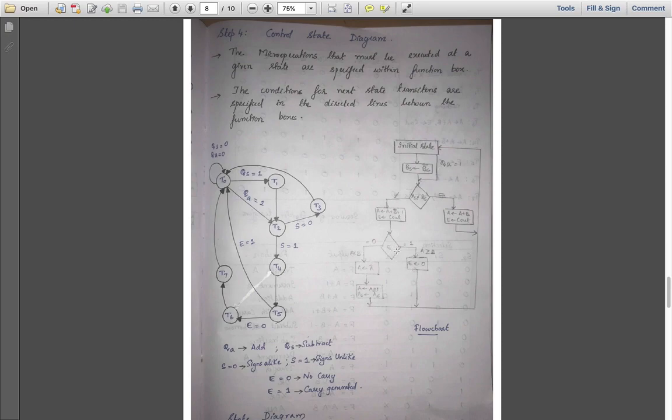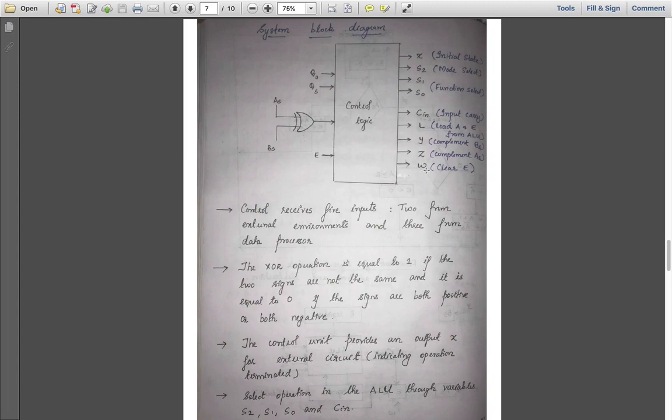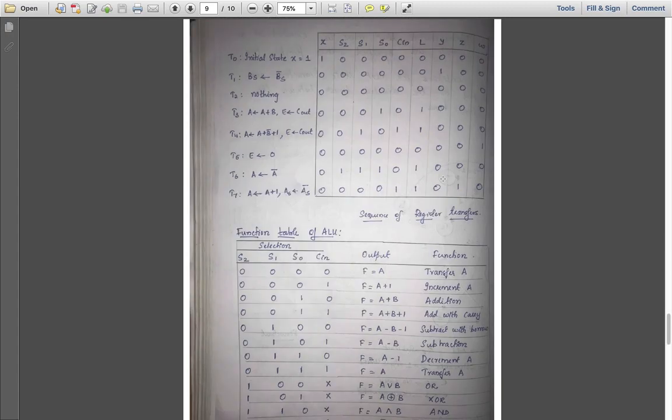That is when you have received the result in this condition. After this 2's complement thing is done, if a carry is there, then the result is directly present in the A register. So you don't need this E register anymore, so you are resetting it. In T5, you are resetting and going back to the initial state. The control line used for resetting E is W. That is the reason why in this particular T5 only W is set and all others remain 0.